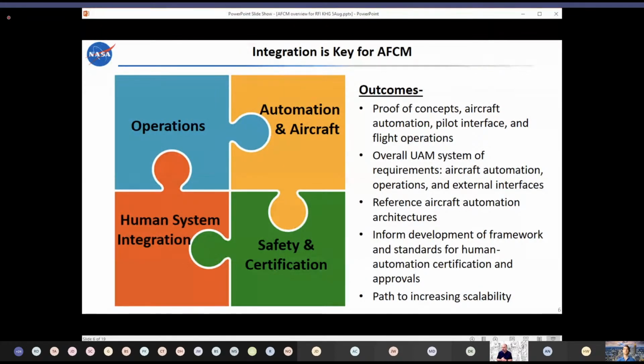A significant part of being able to have robust contingency operations is designing the base aircraft to have fail operational capability. So no first failure, for example, should leave the aircraft in a situation where you don't have a known and safe level of flight performance.